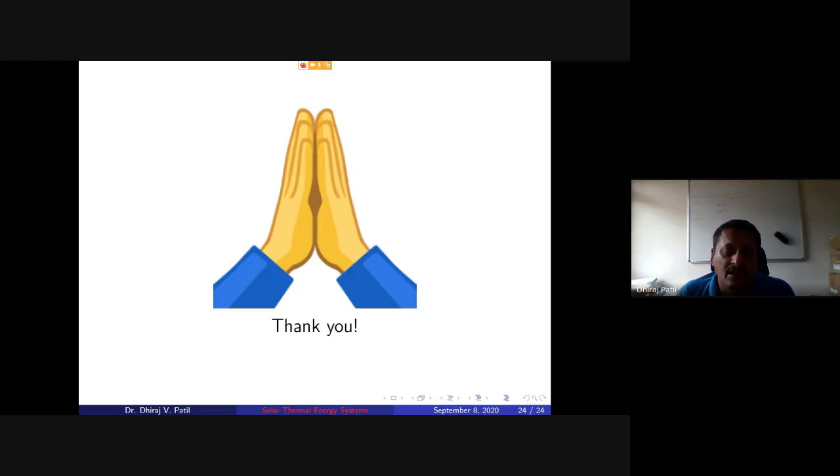So that's why solar photovoltaics are also coming up with what is known as solar PV thermal, where you pass water underneath the solar panels so that the panel temperature itself is reduced. Solar panels have a glass cover, say 2 millimeter thickness, and through this glass cover the sun's radiation falls on the solar photovoltaic material, which is unstable at higher temperatures. So you need to control the temperature. If you control the temperature, you can optimize the efficiency of the solar panels.